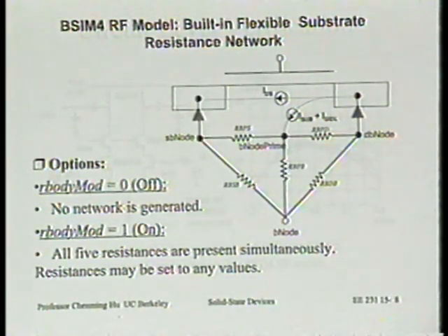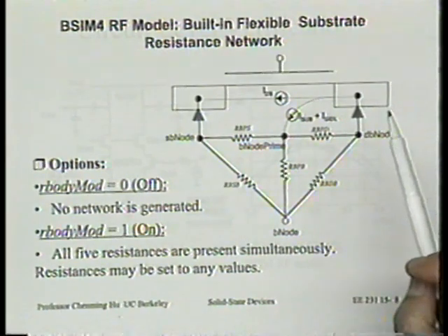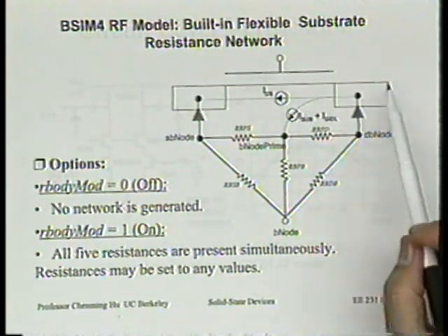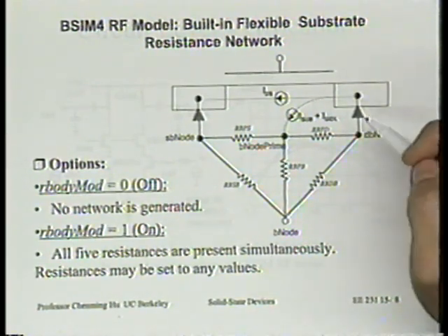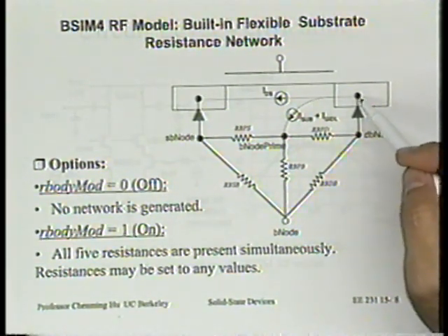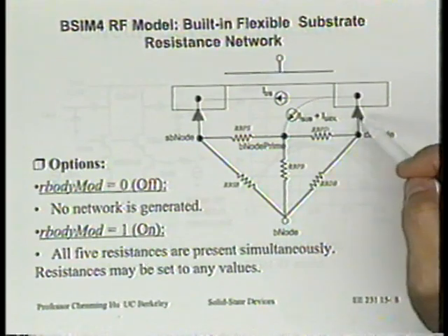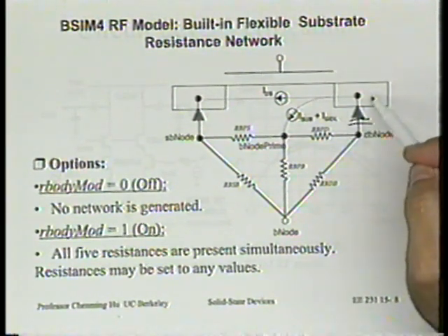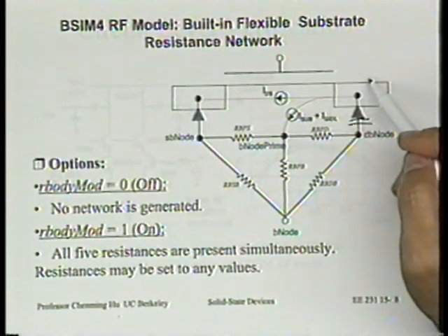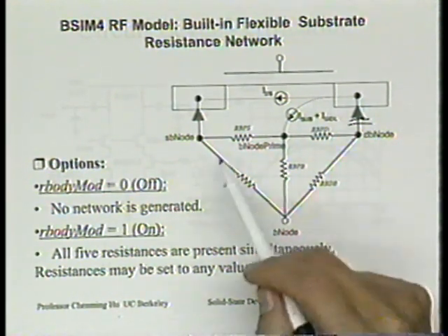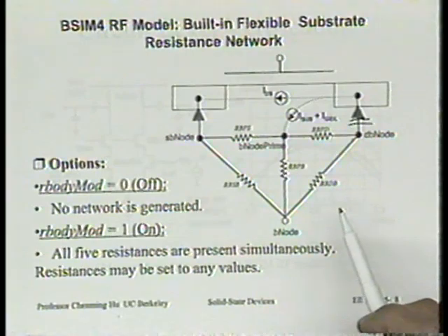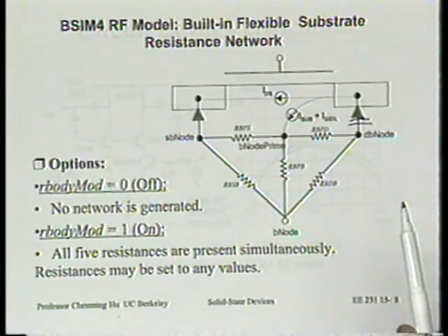We think source is also important, because there certainly could be circuit configurations where the source side is not grounded. And we cannot model this simply as a diode. Specifically, as a result of the capacitance, there will be current flowing from the drain into the substrate. And we cannot assume the substrate is just a perfect ground. We have to model the resistance.